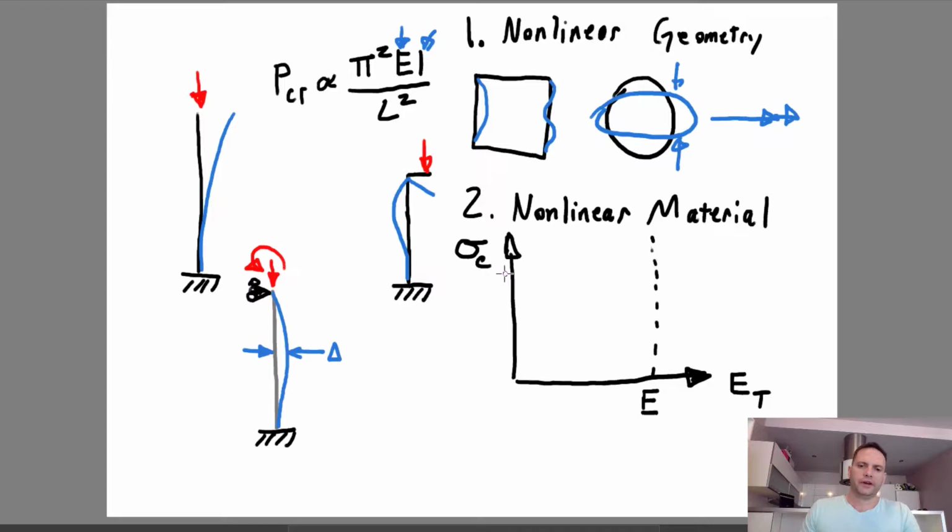Well, here's a problem. You've got another dotted line on this other axis, and this horizontal line is right at the yield strength of the material. When a material is very lightly loaded, it is essentially behaving as if it's not softening. It's right at the value of E here. But as the stress increases and gets closer to the yield strength of the material, you move in this direction on this line.